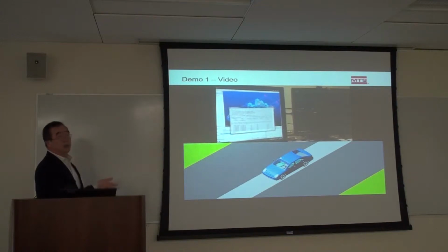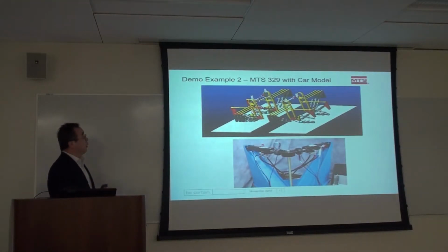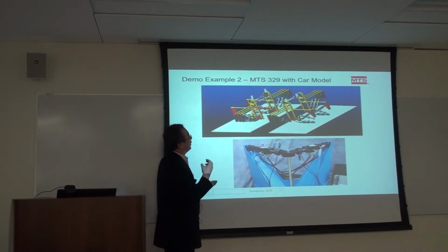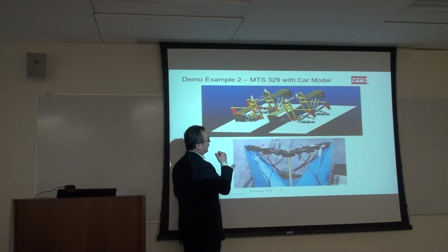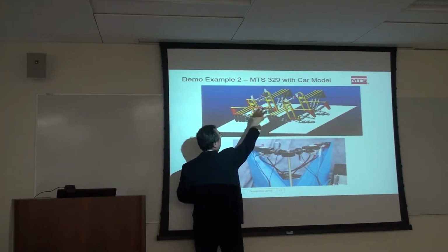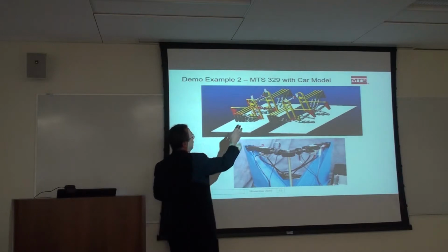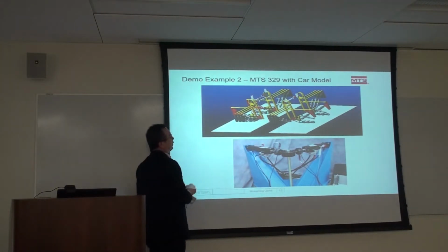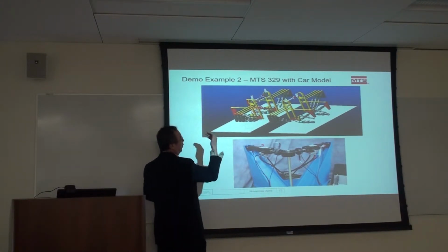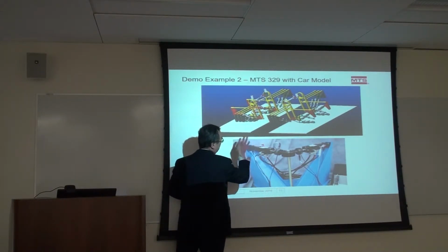So this is an example. With OpenFresco, what we learned in civil structures can be used in ground vehicles. In ground vehicles we do a lot of testing with a sophisticated road simulator. This is one kind of road simulator, spindle coupled, and the vehicle model is on top, with the suspension and the steering, all those. The body is not showing there, and again, we can use OpenFresco to simulate this test, sending the command to OpenFresco to the test.